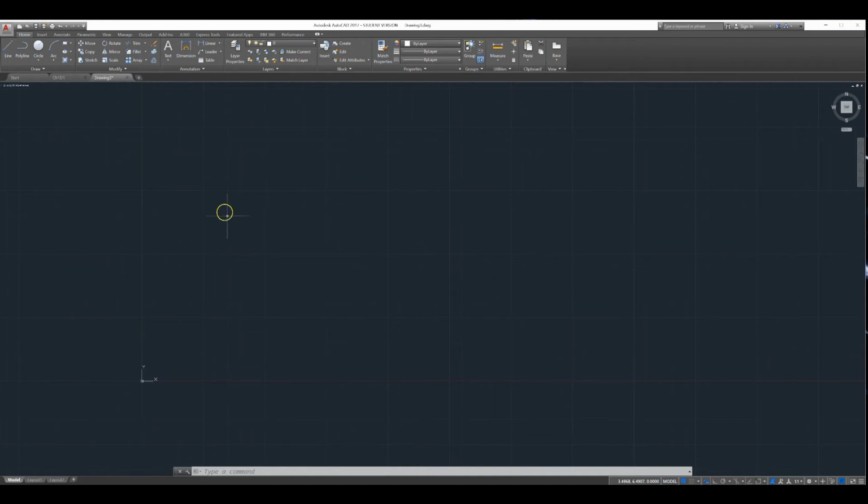And then we'll have 4 more. So I'm going to come up here to the line tool. You can essentially start this anywhere. I'm going to start it right here on this point. Make sure your snap is on. Always want to have your snap on. If you'll notice, when I select the line tool, now it jumps to the points, which is perfect. So I'm going to start here.